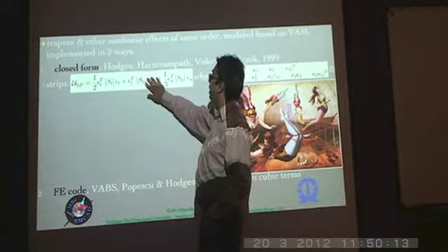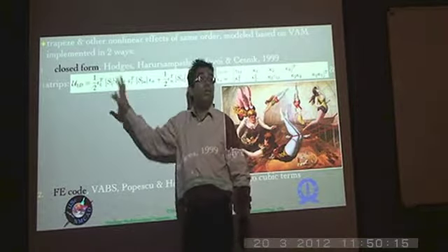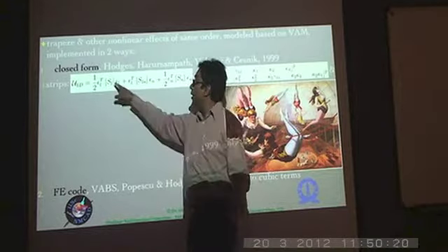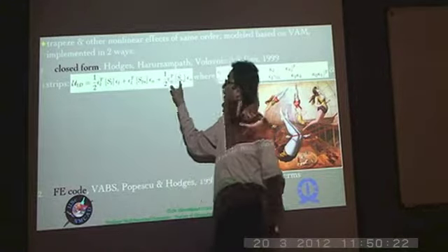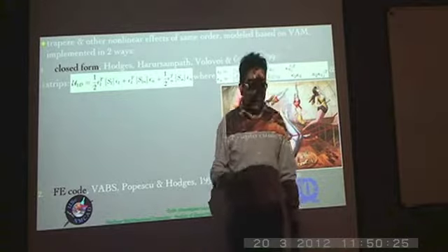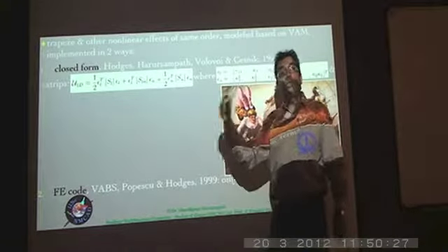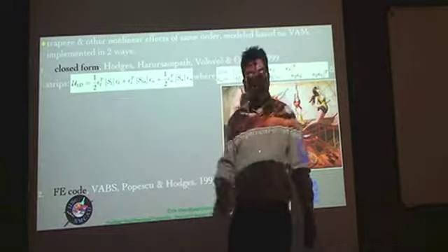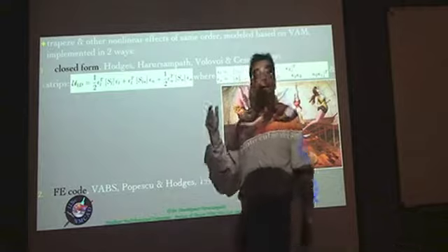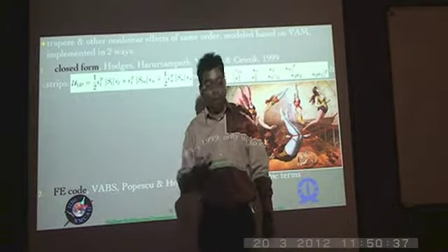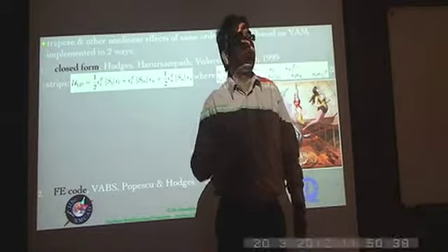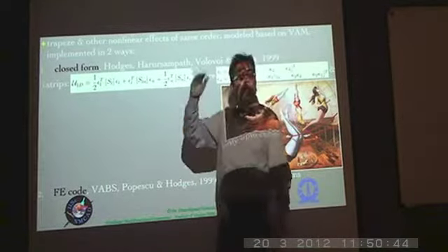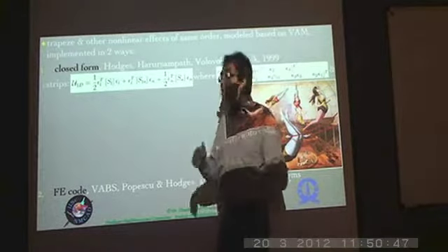Suppose you didn't have the second term and third term, and you had only the first term. That would be a linear cross-sectional analysis, because the way this expression is written, the matrices SL, SLN and SN all consist of constants. Those constants depend, of course, on the material properties of the composite layups that are involved, or isotropic materials, which is of course a special case, and on the geometry itself: the width of the strip, the thickness of the strip, the thickness of each ply in the strip, and so on and so forth.